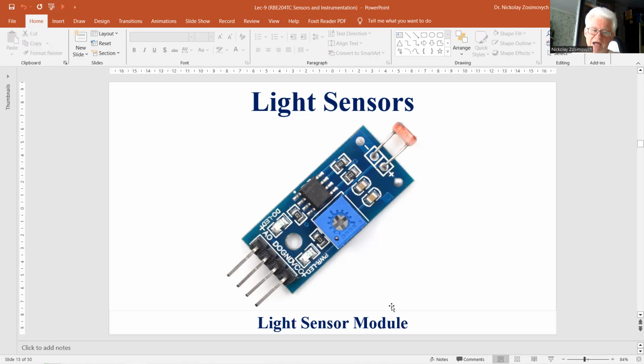CCD camera, area scan. Resolution up to 2048 by 2048 elements. Frame rate up to thousands per second for a low resolution type, gray tone and color. CMOS camera, area scan, higher resolution compared to CCD camera and somewhat worse noise performance.